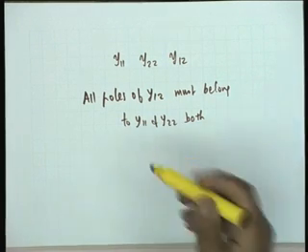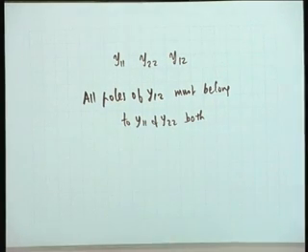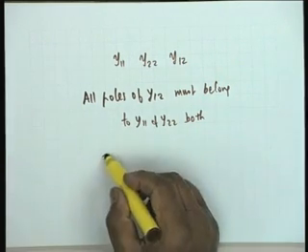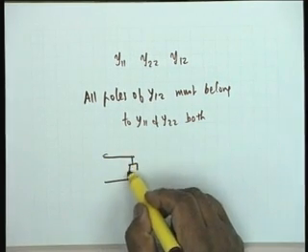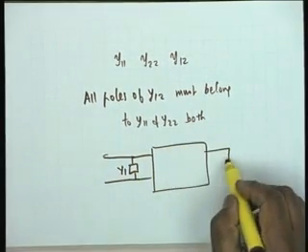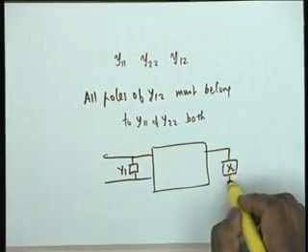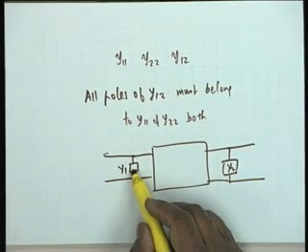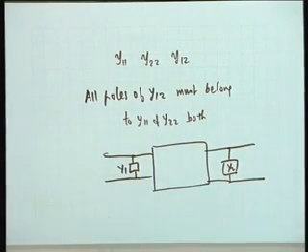And the counter example here is that if you add an admittance y1 in parallel with port 1, and an admittance y2 here, then y1 affects small y11 only, y2 affects small y22 only.